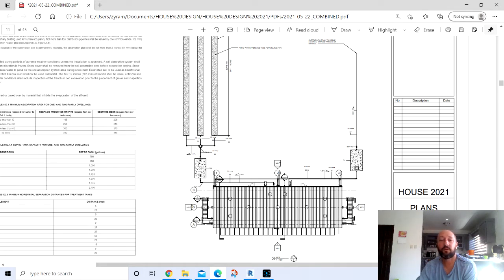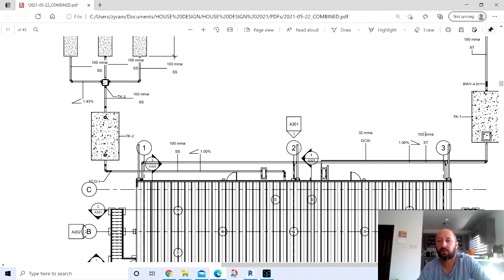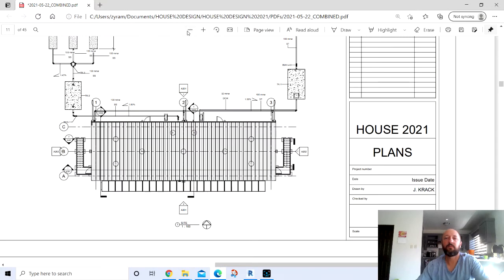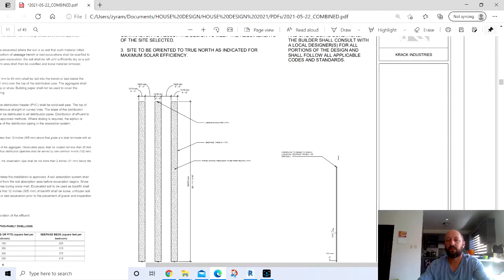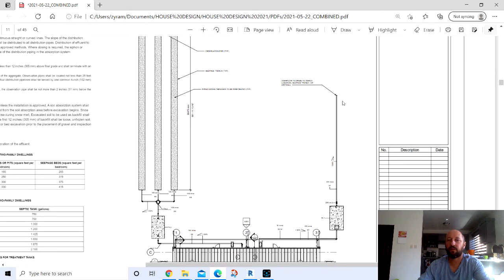Of course, you can see I put the two on opposite sides of the house because you don't really want the waters mixing. So you can see all the stormwater drains over to the cistern, and then all of your sewer drains over to your septic tank. And then of course drainage, you've got a drain to your cistern, an overflow and a drain. Actually, no, I don't remember actually seeing an overflow in the cistern. But anyways, you've got an overflow and then a drain.